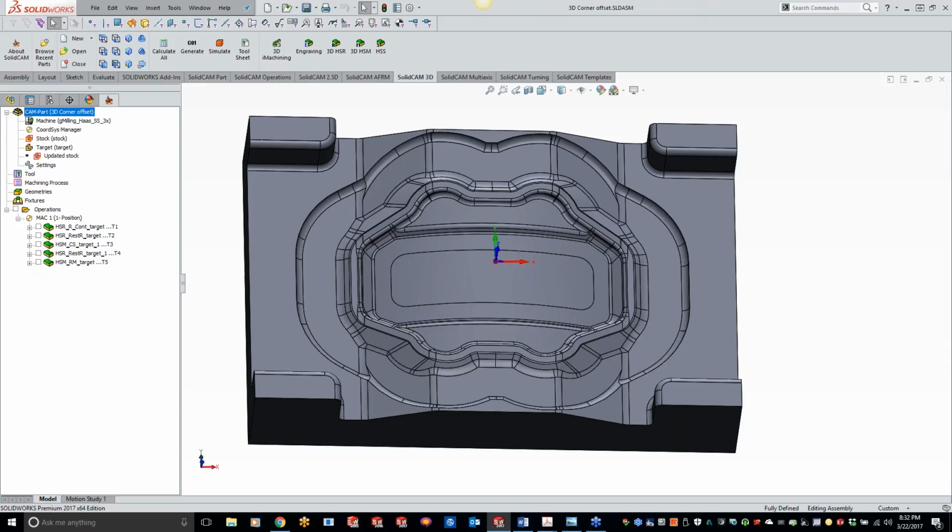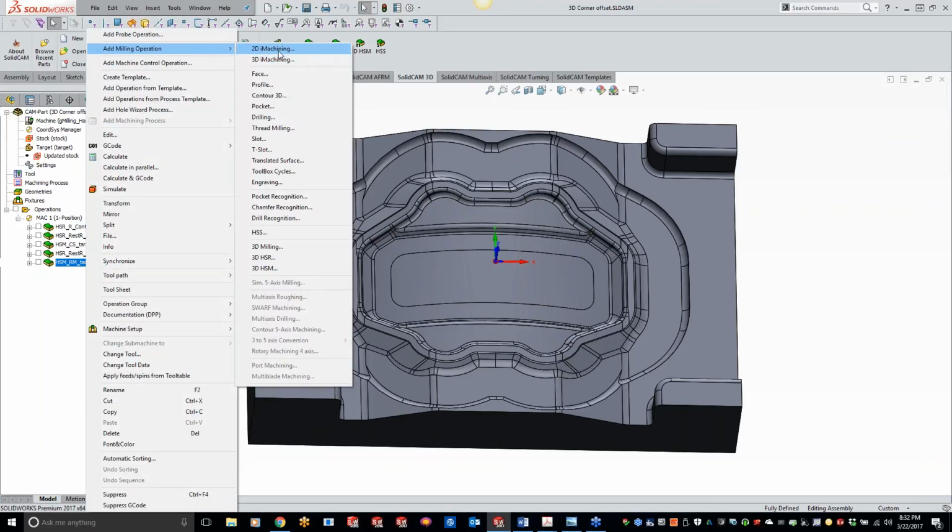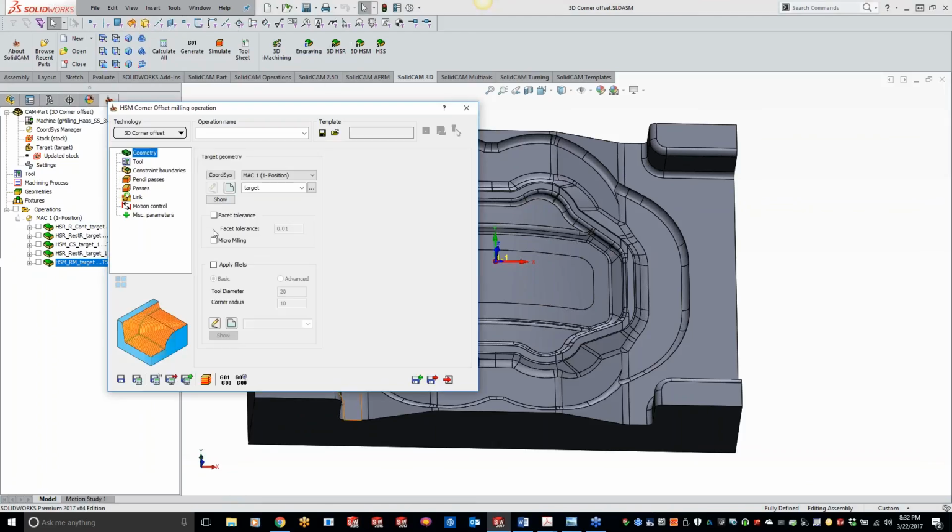So it's a combined toolpath of all these different operations, and basically it follows your surface, using a pencil mill strategy. When we were talking about the parallel pencil milling passes, with the parallel you could extend it off, say 5 up the wall and 5 on the flat bottom. Well, now we're doing that through the entire part, if you guys can kind of imagine that. So let me start programming here and get some toolpath on, and I'll show you what it's doing.